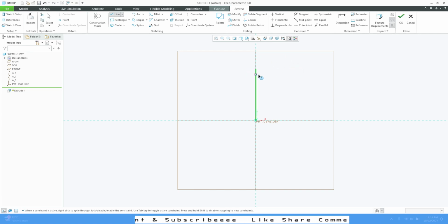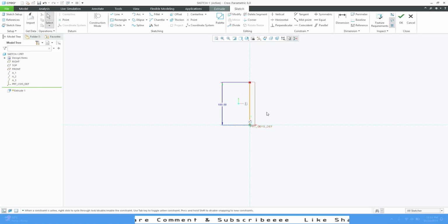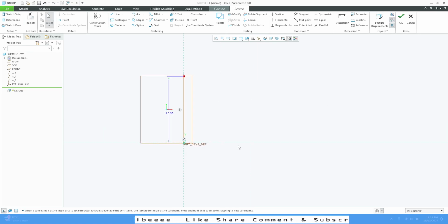It will cancel the line propagation from that last endpoint. After that, the line tool will still be active. As you can see, I can draw one more line, but I don't want to draw, so I will middle mouse click once more, and we have created our first line. Now this line I want to define, let's say 100. So we are setting the stage for our sketch.